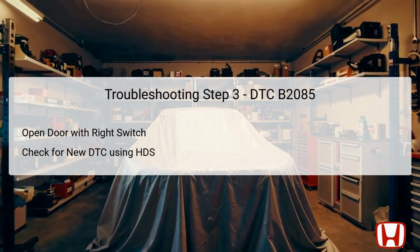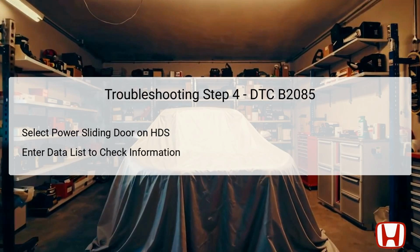Alternatively, if no codes are generated, it may indicate an intermittent failure, which suggests that the system is currently operational, but should be monitored for future issues. Documenting these findings accurately is essential for making informed diagnostic and repair decisions moving forward. At this juncture, you will select the power sliding door function from the Honda Diagnostic System, HDS, and access the data list.